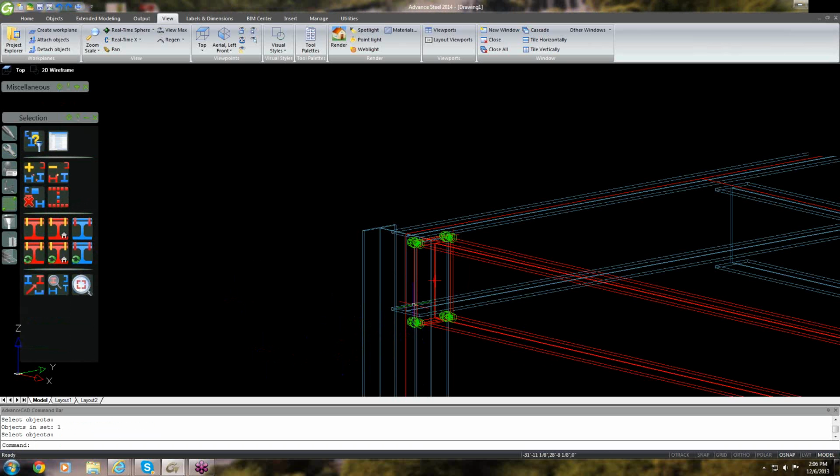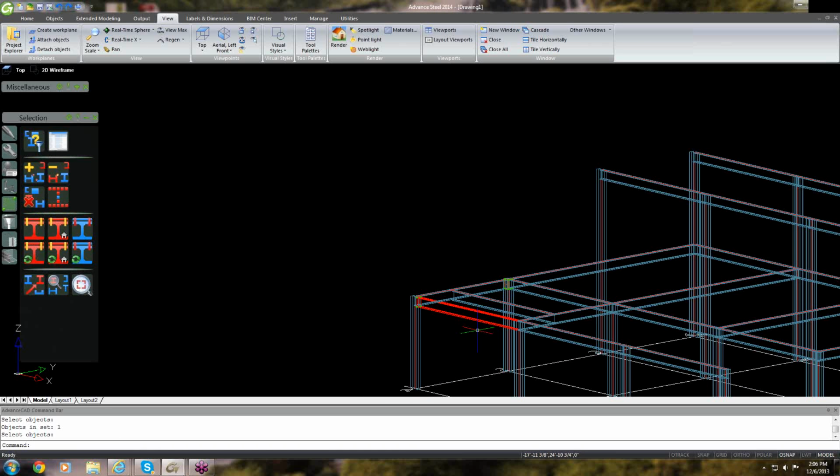Can you zoom out? Because it takes a column here to get both of them. You know, this plate, that's the point. You need to have the same situation to get advanced copy working. In this case, you have a beam and column. Oh, I see. So that's why advanced doesn't know where to put that plate, because there's no column there. Yeah, it is confused by that. Okay. No, it makes sense now. Yeah, we should have gone to next column.